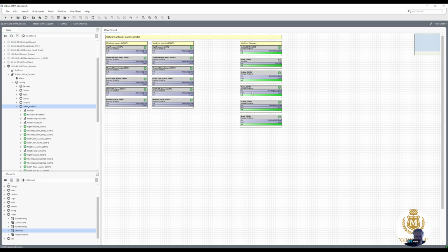The mode for ground source heat pump 1, whether it's heating or cooling mode. And enable ground source heat pump 2. That's just via Modbus to the ground source heat pumps. Naturally, we're doing the hardwired ones for the pumps to enable the circulation, the ground source circulation pump to run. So that's it for now, until I get to site.